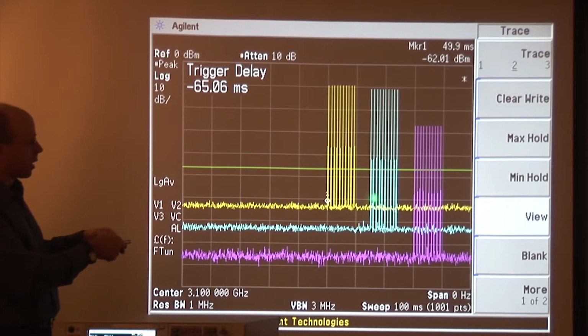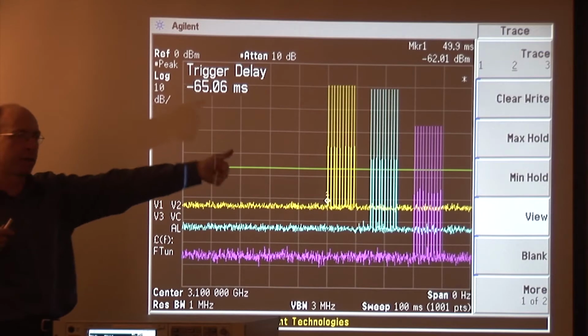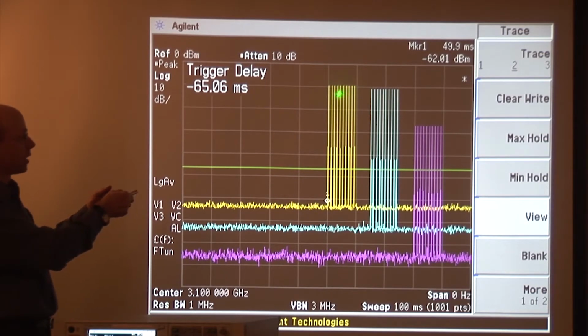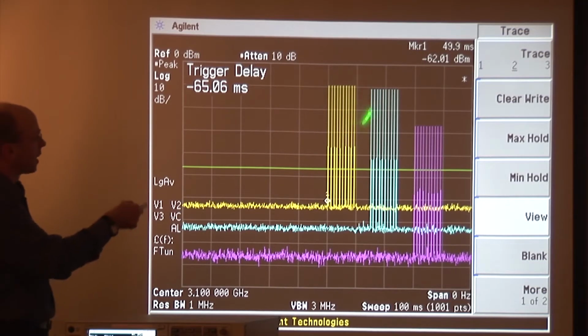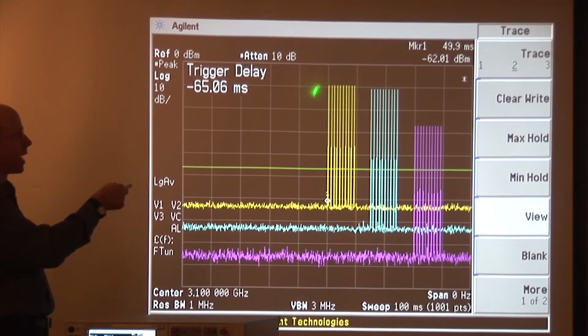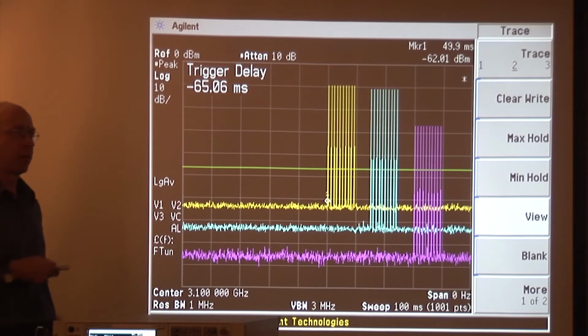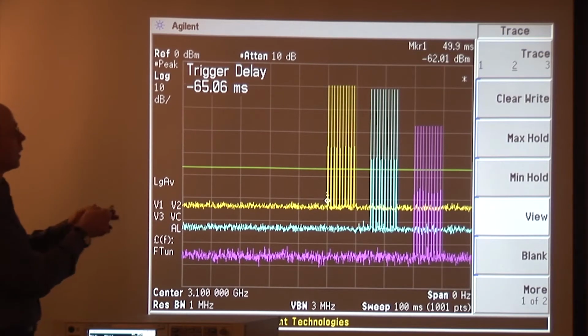So here we are in the matched filter bandwidth, 1 megahertz, which matches 1 over 1 microsecond. And what's our dynamic range? 10, 20, 30, 40, 50, 60, plus a little, 62, 63. Okay, so 62 or 63 dB of dynamic range. Now we go to a wider bandwidth than that. We don't get any more power at the fundamental, but the spectrum analyzer noise came up at the rate of 10 log of the bandwidth, so now we get 10, 20, 30, 40, 52. So we lost 10 dB of dynamic range by going to a bandwidth that was wider than 1 over the pulse width.